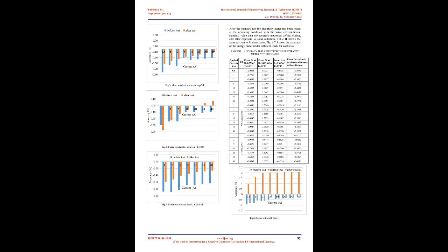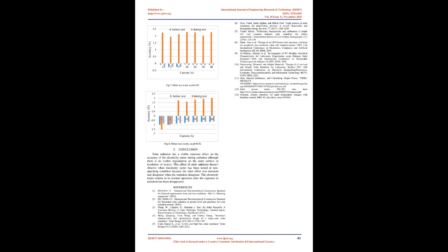The electricity meter was placed inside the climatic chamber, and its accuracy was measured at a radiation value of 1066 W/m2 plus or minus 8.5% and ambient temperature of 55 degrees Celsius. By considering the temperature generated from the climatic chamber in addition to the output temperature from the halogen lamps, an external temperature sensor was placed inside the chamber over the test area to control the temperature by changing the adjustment of the climatic temperature, and it was noted that the ambient temperature inside the chamber reached 55 degrees Celsius when the chamber temperature was adjusted at 33 degrees Celsius.